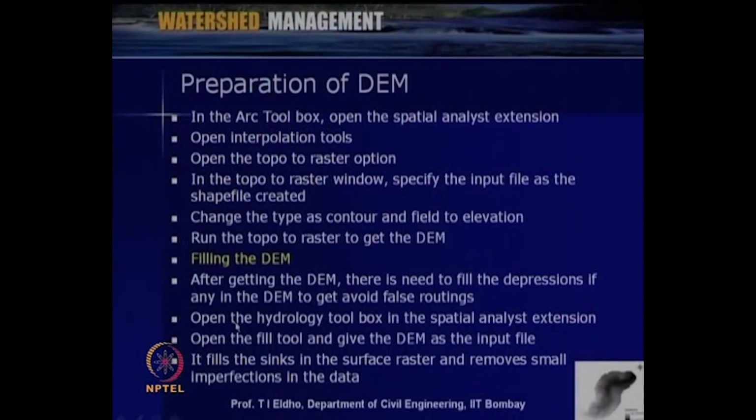Here, we open the hydrology toolbox in the Spatial Analyst extension, then open the fill tool and give the DEM as the input file. It fills the sinks in the surface raster and removes small imperfections in the data. So, depending upon the case, if there is a drastic change in the given data, the filling operation will rectify this, so that we have a better digital elevation model.